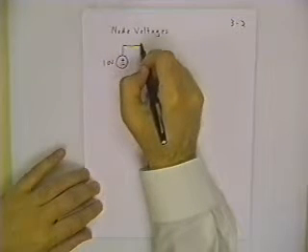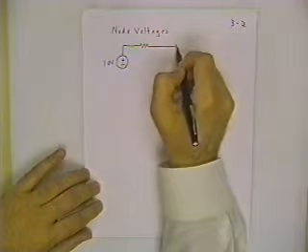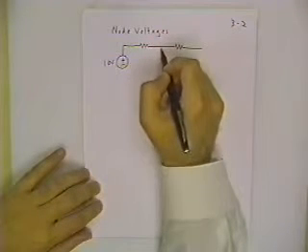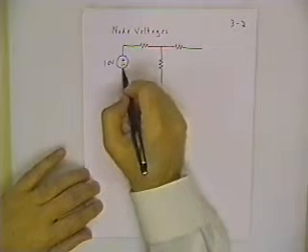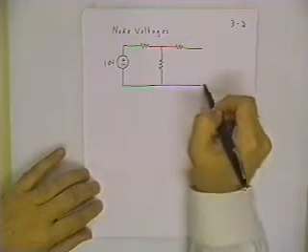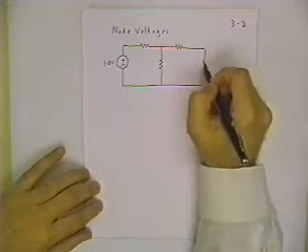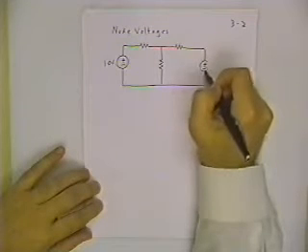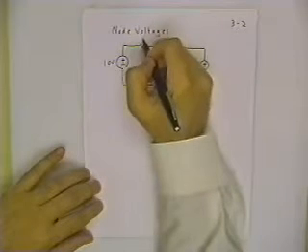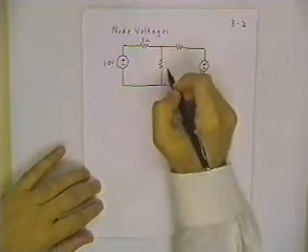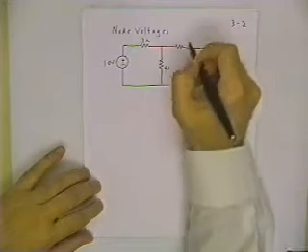One thing that should be pretty clear is regardless of the solution technique you use, you should get the same answers. When you have the luxury of a lot of time, that's really the way to figure out if you've got a circuit solved completely and correctly: check out all the Kirchhoff laws, and then once you've finished with one technique, solve the circuit again with another technique and make sure you get the same answer.